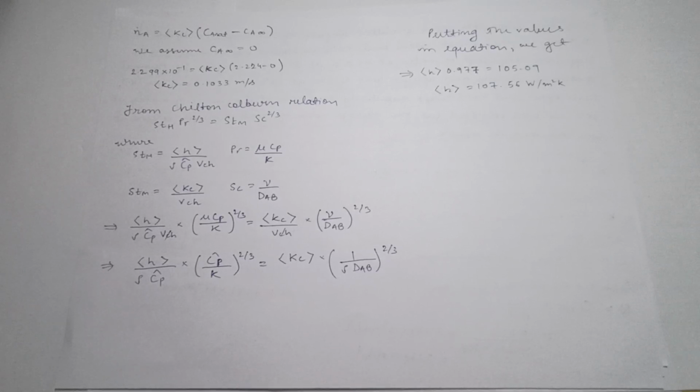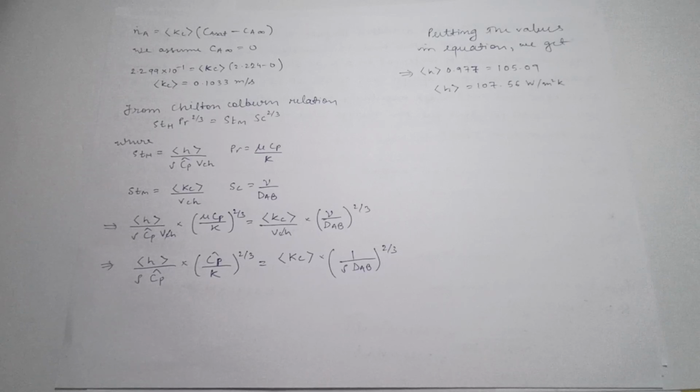And lastly, the mass transfer coefficient, which was 0.1033 meters per second. After substituting all the values, we get the heat transfer coefficient as 107.56 watt per meter square Kelvin.